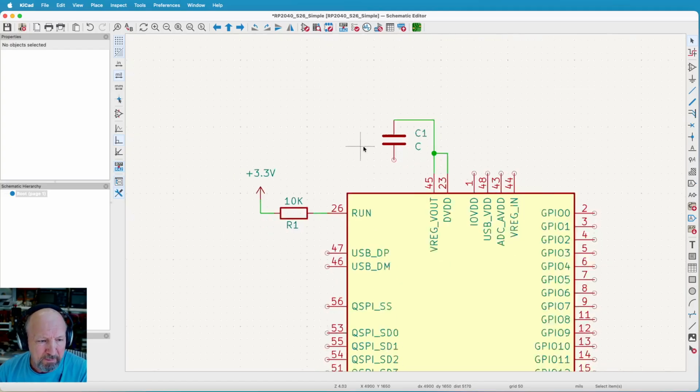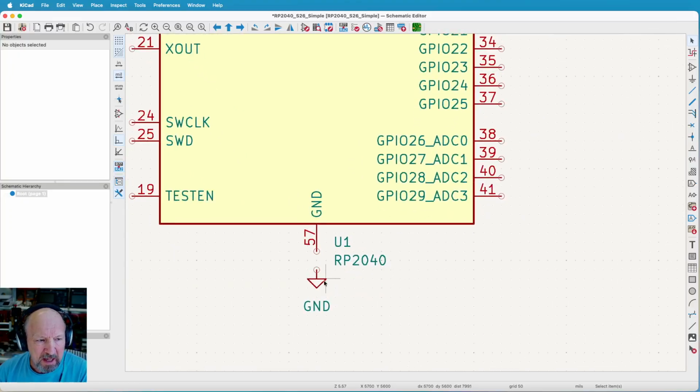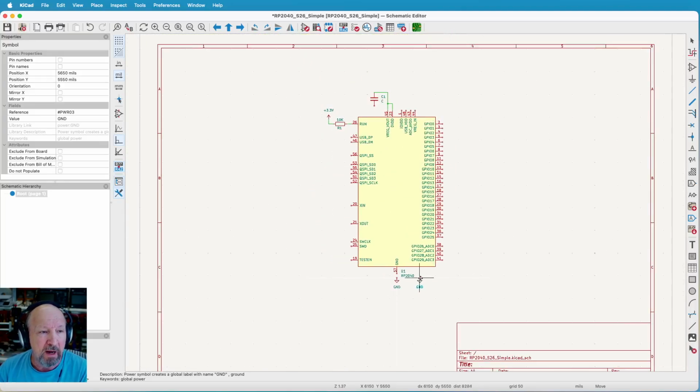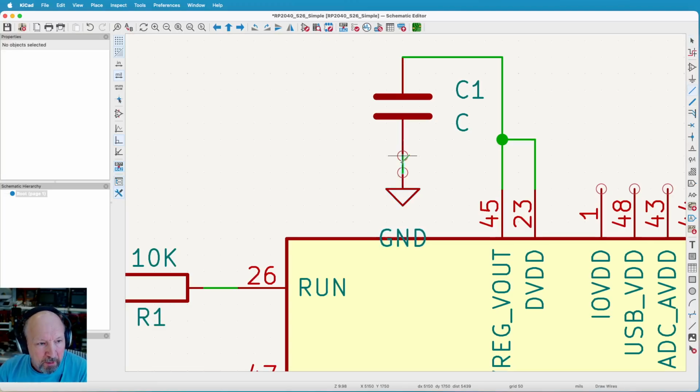So I've already got a ground down here. Let me come over here. I want that one to stay there, but I want a copy of this. So if I put the cursor on it, and I do, on my machine, I'm doing Command D for duplicate. So that'll give me another ground. And so I zoom out, go close to where I want it to be, zoom up, and put it here. I'll draw the trace so the circles go away.